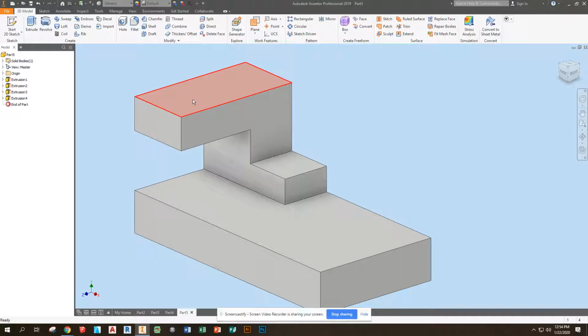Now I know I've got a single hole up here and 2 down here in front. I'll do those right now. Now here's where it gets a little odd. There's 2 different ways to do holes. Instead of what I did on the other one, where I just used the extrude cut, I'm going to use the hole tool here, just so you can see how it works.